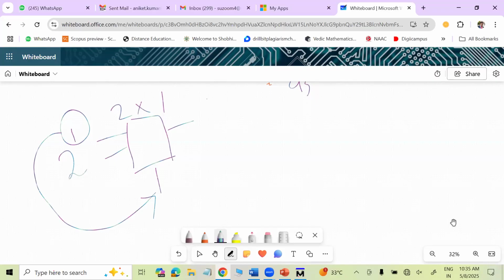So considering the same, let us see how it will be programmed. Suppose this is S, this is A, and this is B. So S is obtained, Y is written in terms of A and B as A if S is at 0 position, B if it is at 1 position. Then it will be written as A into S plus B into S complement. Directly you can program this.